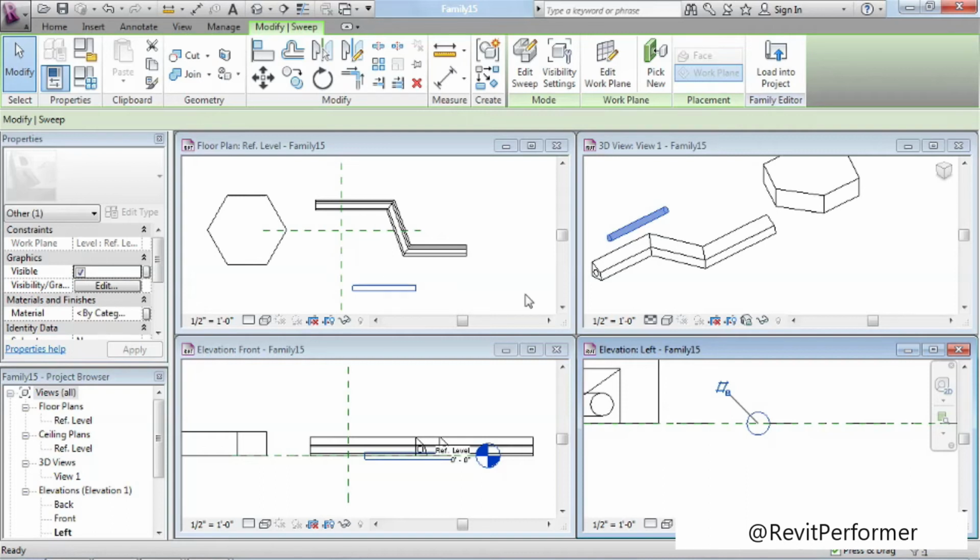And you can see that when I finish, it doesn't look much different than what I could create with an extrusion. So the two main differences are, if I would prefer to sketch the path and have grip points and be able to draw it graphically on screen rather than use properties on the palette, notice that there are no numbers over here now. You can't type in a depth like you could with an extrusion. That's one difference in the sweep, and the other is the different options that you have for the profile. We will do a swept profile example in a later movie, so for now I'm going to skip that one and just stick with the sketch.